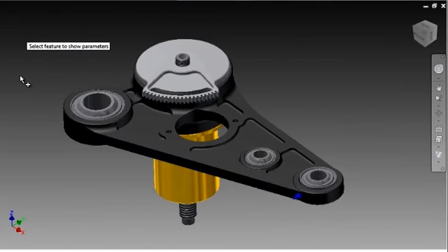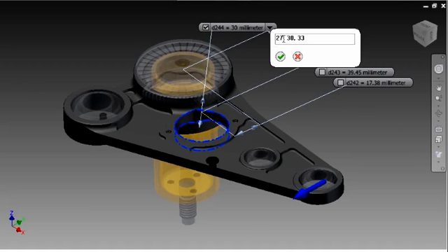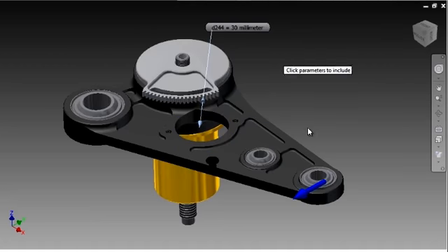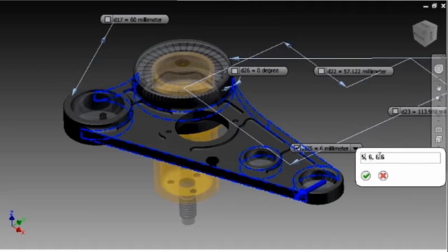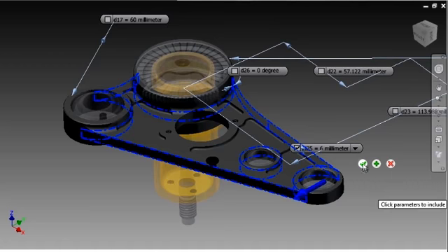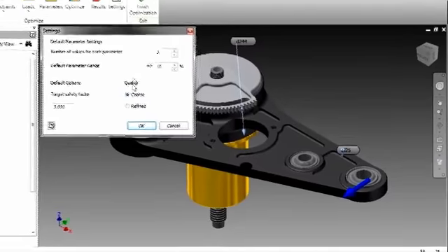Next, we will use the same design parameters that Inventor uses to store the dimensional values for part features. However, we are going to use Autodesk 360 Optimization to specify a set of alternate values for each of the parameters selected, which, when combined, will define a range of feature and part sizes. From this range of values, the optimization service will essentially build iterations of the assembly and then test them against the target factor of safety that we will set here.